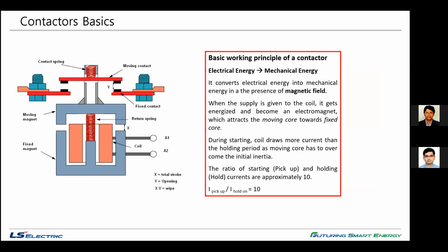Now, a very important part: what is the basic working principle of the contactor? It converts electrical energy into mechanical energy. When supply is given to the coil, current passes through the electromagnet or coil, a magnetic field is produced which attracts the moving core of the contactor.